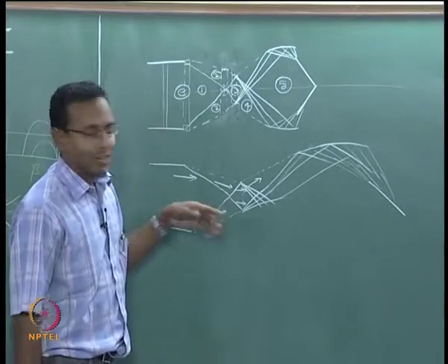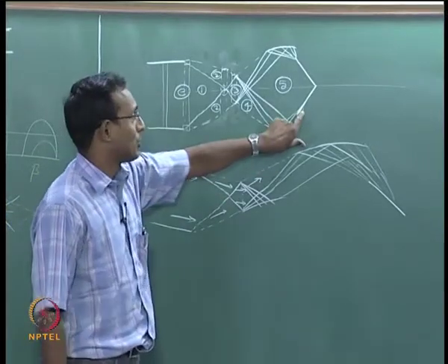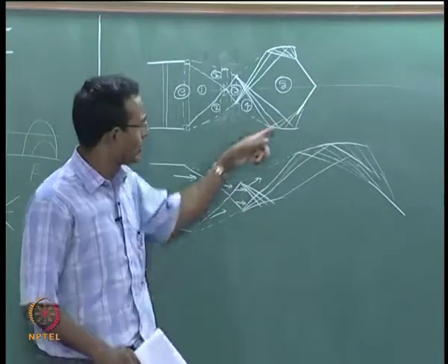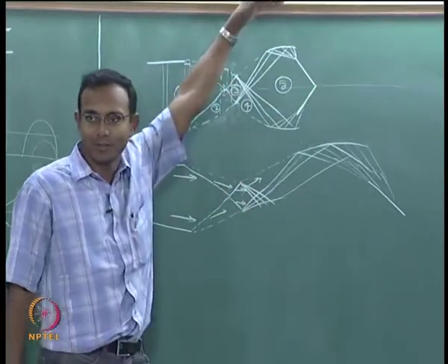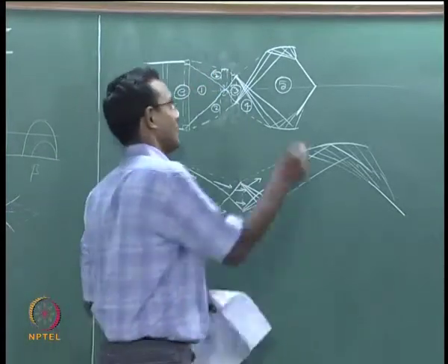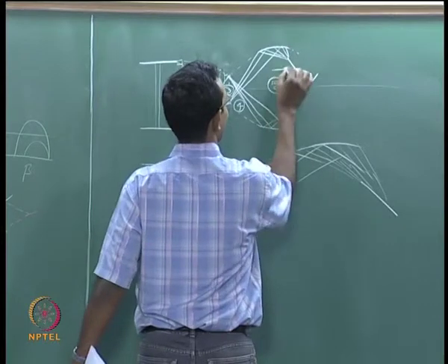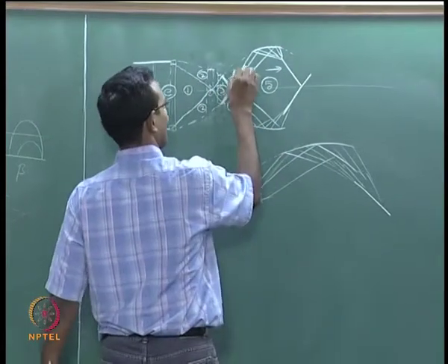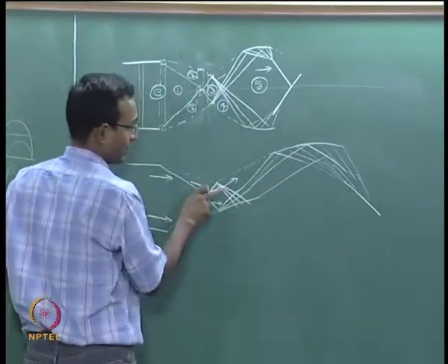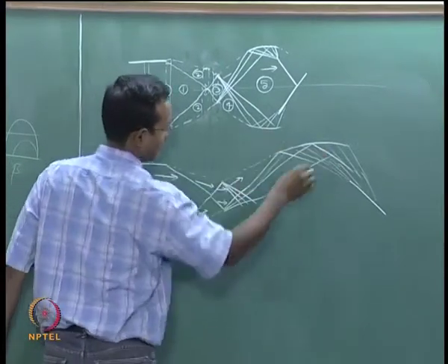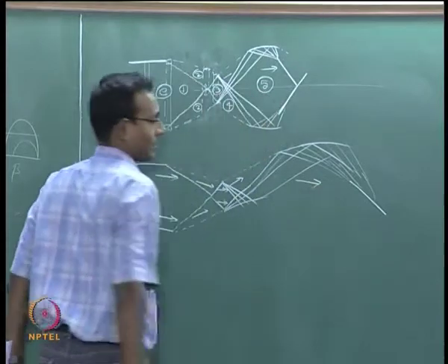Now what happens? All these compression waves came together, formed a shock, and that shock is running through. It cannot stop halfway, it has to go all the way till it finds somebody adamant who will replace them. So, they will keep on running again. What happens here? The flow was going straight. Oh, I have to draw the angle. This vector that is going up is now going to see this expansion, which is going to tell it to pull that way, so it will become parallel again.